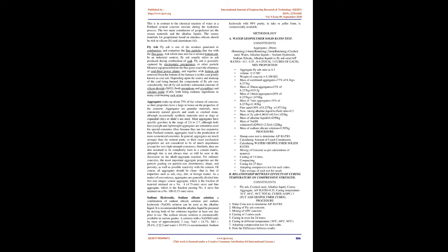The last term in the equation reveals that water is released during the chemical reaction that occurs during the formation of geopolymer. This water, expelled from the geopolymer matrix during the curing and further drying periods, leaves behind discontinuous nanopores in the matrix which provide benefits to the performance of geopolymer.